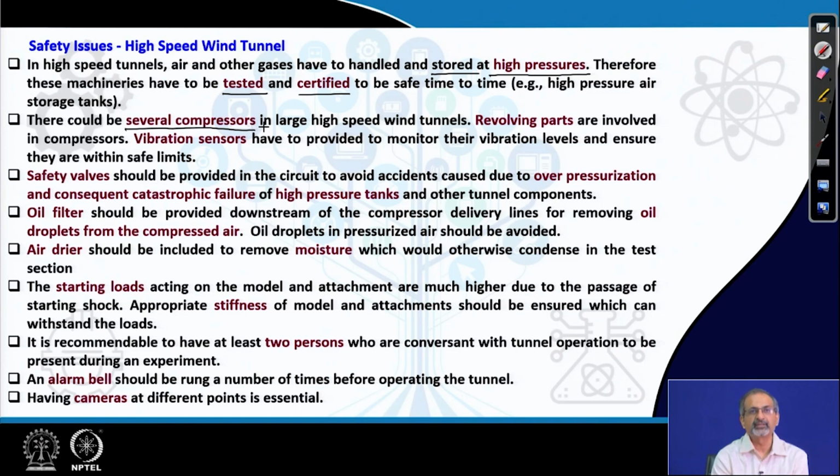Usually there are several compressors in large facilities, and these have revolving parts, and vibration sensors have to be provided to monitor their vibration levels and ensure that they are within safe limits, otherwise they need to undergo some maintenance. Safety valves should be provided in the circuit to avoid accidents caused by accidental over pressurization and consequent catastrophic failure of high pressure tanks and other components. So, safety valves are a must.